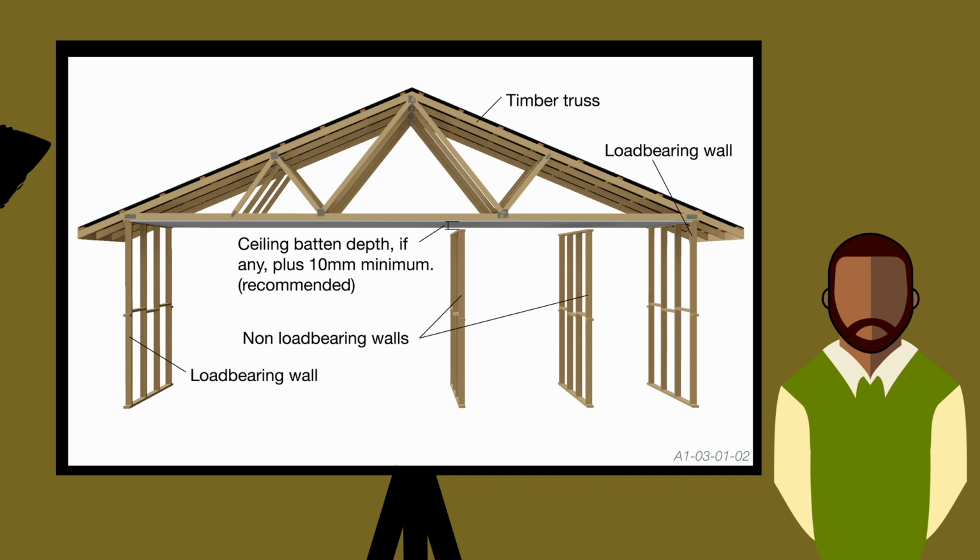You might not be able to find those. You might be better off using 2x6s even on the interior. And if for some reason you can get away with using 2x4s in the interior and you find some straight ones, by all means. If it's non-load bearing, I personally don't really care.